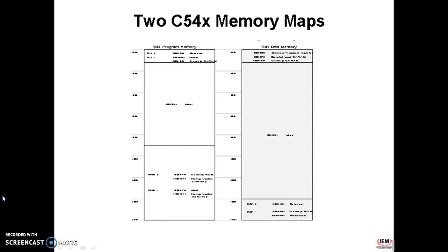Now for the memory mapped register, the data memory space contains memory mapped registers for the CPU and the on-chip peripherals. Those registers are located on data page 0, to simplify access to them. The memory mapped access provides a conventional way to save and restore the registers for context switch and to transfer information between the accumulator and the other registers also.